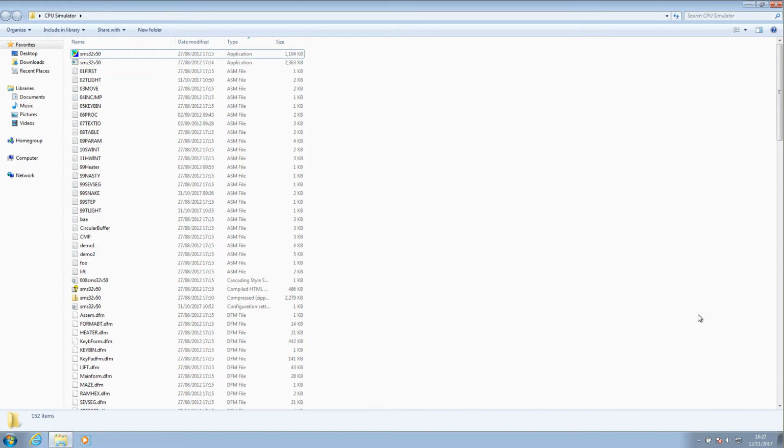In the last video we configured the CPU Simulator to output the United Kingdom traffic light sequence. This worked well. We got the traffic light sequence pretty much correct, but the problem was it was transitioning very fast. That relates to the clock speed, and we can actually slow that down. If we slow it down to 1 instruction per second, then it looks about right speed-wise, but the problem was where we had the red-green light sequences. We need to have some form of delay there in order to allow the traffic to flow. And that's what we're going to look at in this video.